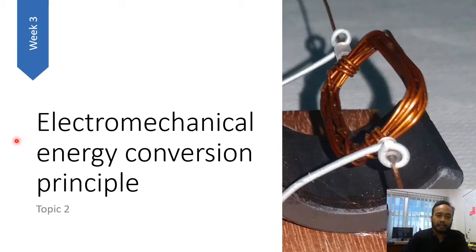Last week, to recap a bit of what we have seen, we looked into a magnetic circuit. We defined what flux linkage is, and its relation with what we call reluctance. Reluctance is the measure of how difficult it is for the magnetic flux to go through a certain section of a magnetic circuit. We have seen that the section where you have an air gap is the most difficult. All the MMF, or magnetic force, that is produced inside your winding.